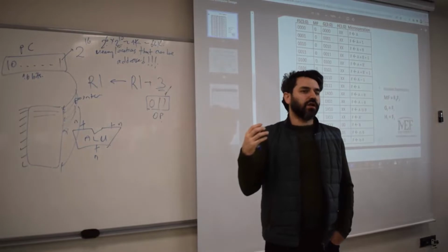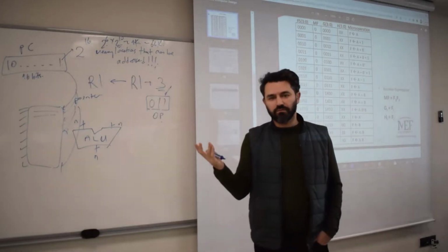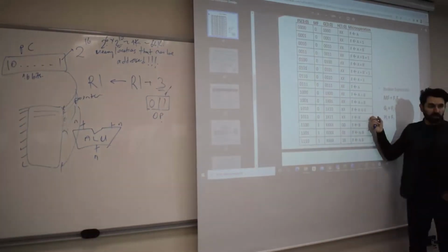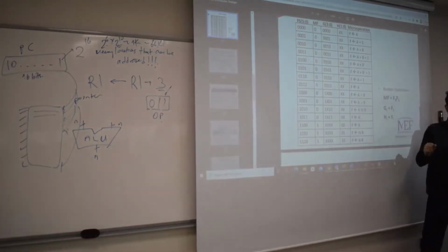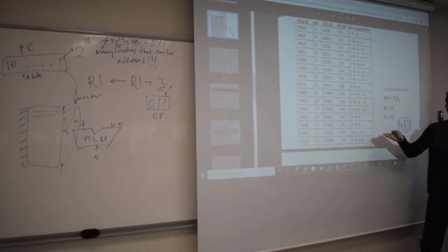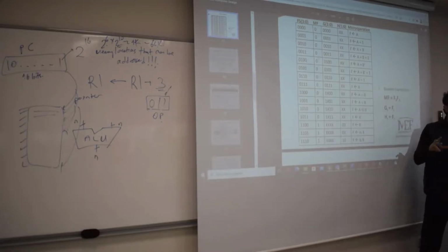You may ask yourself, oh, this is too much time for just a specific NAND, right? So you may want to introduce a NAND here that would take only a single cycle, okay? You would think that's just a simple change in the instruction set architecture, and that probably would not change the hardware too much. Yeah, the data path and the control bits may not change too much, but the instruction decoder will change a lot.